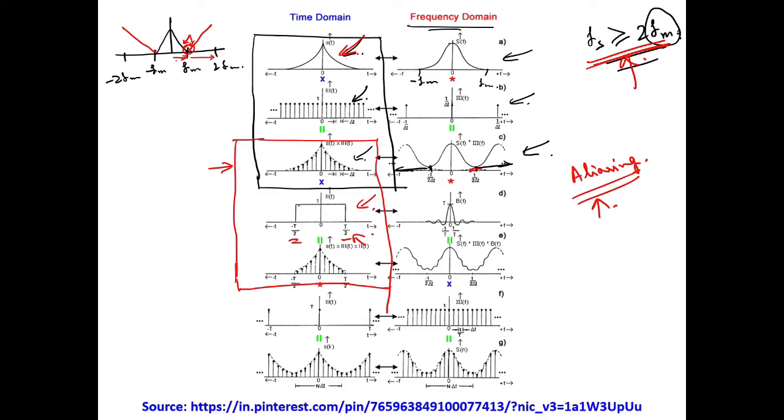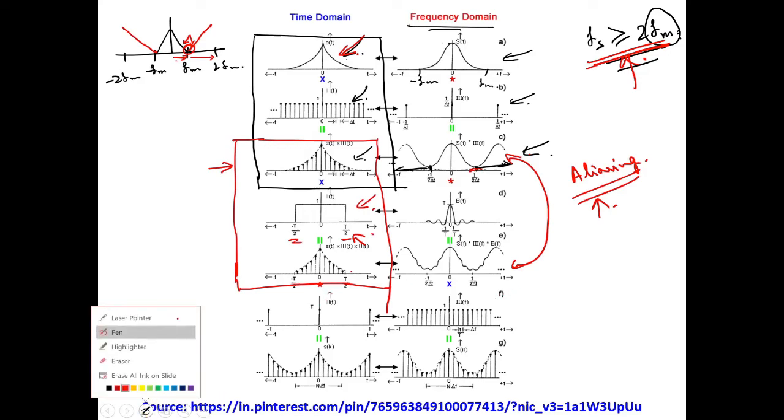We are just cutting a piece of the signal from there, creating a window in the time domain. Once we do that, we have time limited the signal, and you can see the signal is still repeating itself. Now the next thing is, after so much processing done in the time domain, we now need to go to the frequency domain.